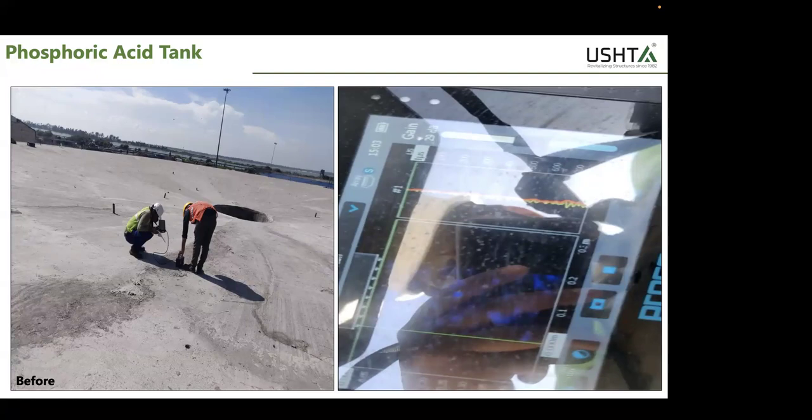This concrete, roughly when was it done, sir, this project? So this was freshly done. I mean, immediately after concreting, they realized. No, the original construction, the original project. Yeah, original only, sir. This was about 7-8 years back. Self-compacting concrete was available at that time. Sir, it was there. So that is the exact problem. The consultant did not recommend that. Secondly, the consultant suggested a wrong test to be conducted. UPV and hammer cannot be used in densely reinforced concrete. So this was a disaster, sir.